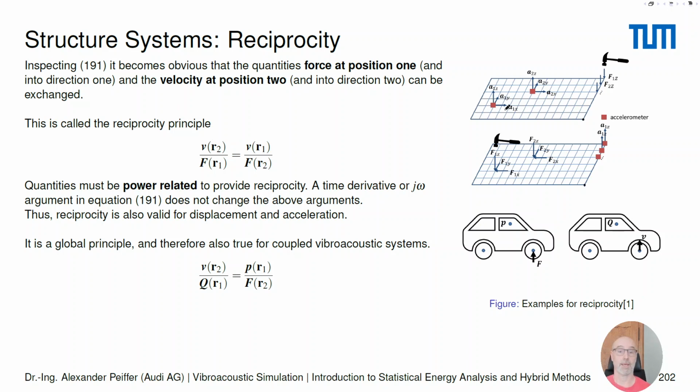So from the formula it is exactly the same if you excite here and take the frequency response there at the plate, or you do it exactly the other way around, so that you excite there and measure the acceleration here at the plate. And this is what we call the reciprocity principle. So the relationship of displacement at 2 to force at 1 is the same as the displacement at 1 related to force at 2.